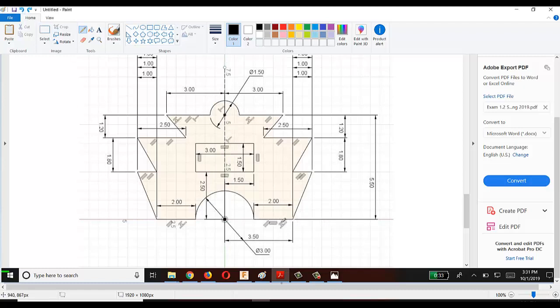This way we are going to design this half circle. And as you see in that sketch, the constraints or relations are also shown. This is parallel, this constraint we call collinear, this we call horizontal, this constraint we call vertical. There are a lot of constraints. This is again parallel, this is perpendicular, this is also perpendicular. In the first introduction video I talked about these constraints. The concept of these constraints is very important. If you have some confusion about them, you can go there and watch the first two or three introduction lectures about it.